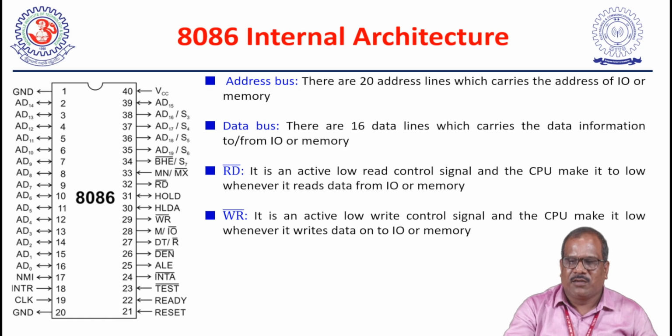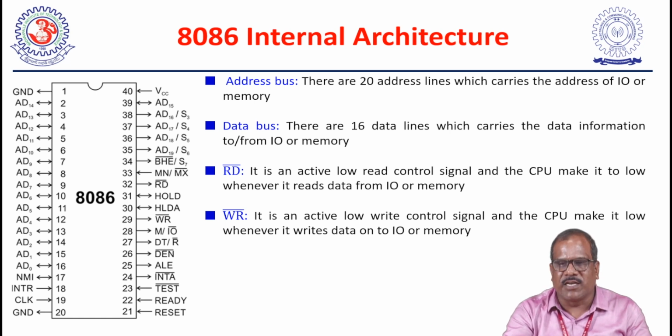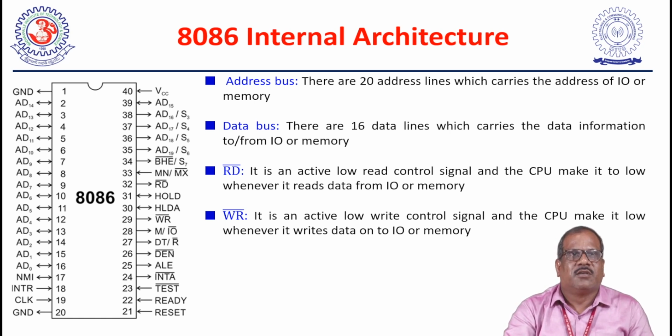So here it has a 20-bit address line, a 16-bit data line, and various control signals. I'm going to discuss like this. First, the multiplexed address data lines.